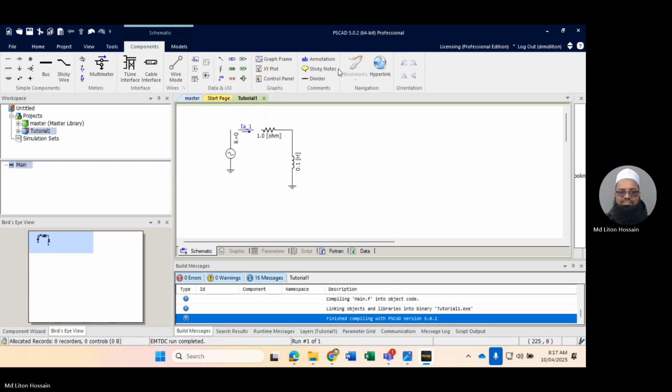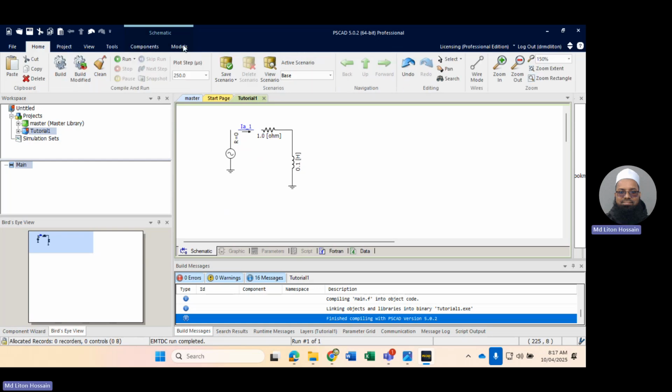and now bring the wire, it's the wire, and connect it. So make sure that, I did a mistake, so if you want to stop, you have to right click. This is continuing, so if I left click, in this place you see the extra wire, so I'm going to undo it here, do it again and right click. Okay, do it here again and right click.